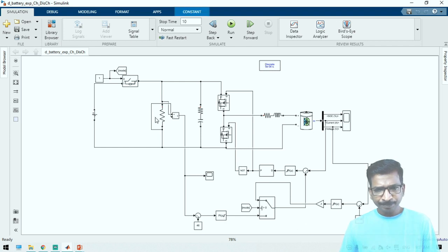See here, if DC input is available, then the load should receive power automatically from this DC source. If it is not available, then based on its value, even if it is a 12 volt, it should receive 48 volts as the rated voltage. So like that we have to implement another loop.